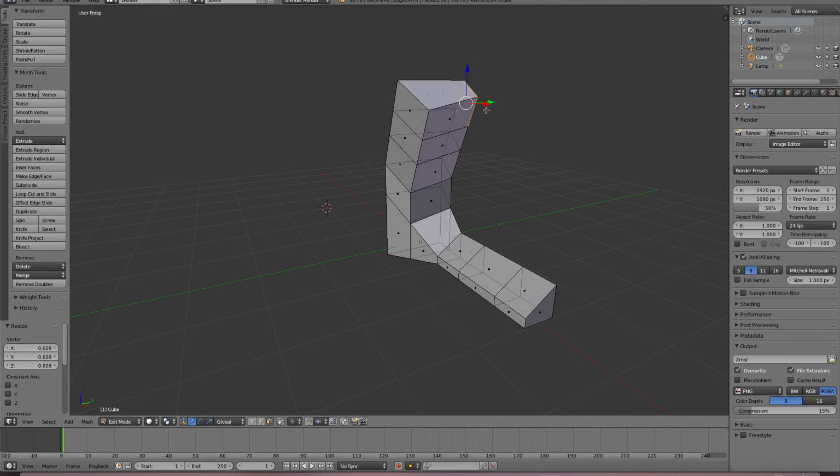Now let's say I want to select an object, and if I draw a box around it, let's say I just want this point and a few others, and I don't want all the rest of this. You'll see that that's very difficult to do with a box. So if I switch to vertex mode, the trick for that is to select one of the objects, hold the control key, and draw a selection around the area you want to select. Okay, that you can see is very easy to do. You just hold control, draw a selection, and that will select whatever's in that circle shape or whatever shape you create. Doesn't really matter.